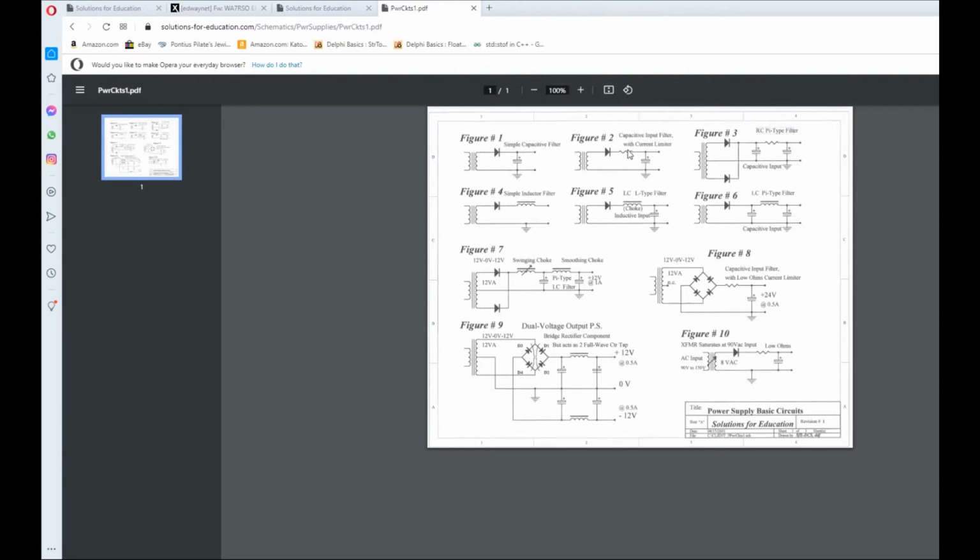We come over here and we say, now that I know about that, guess what? That's why this resistor is in there. That resistor is in there to limit surge current. That's what it's there for. It might only be a half an ohm. It might be 3, 4, 5 ohms. It might be a resistor fuse. If you've ever seen them, they look like an ordinary fuse, or maybe look like a ceramic resistor, but it's really a fuse. All right.